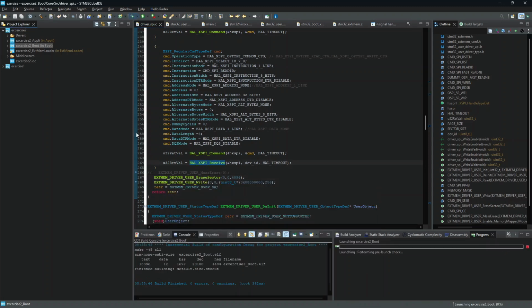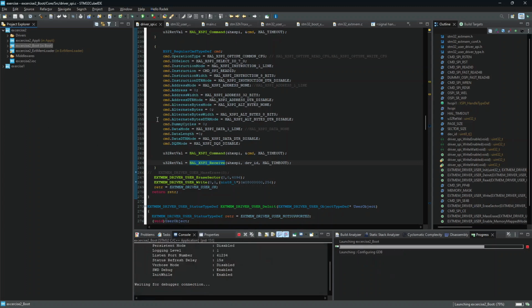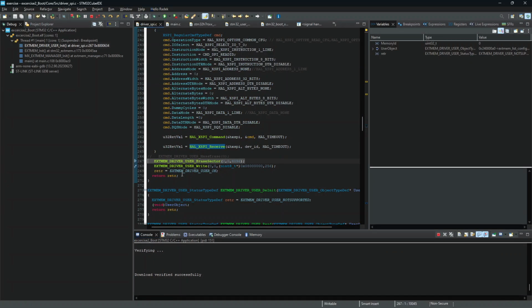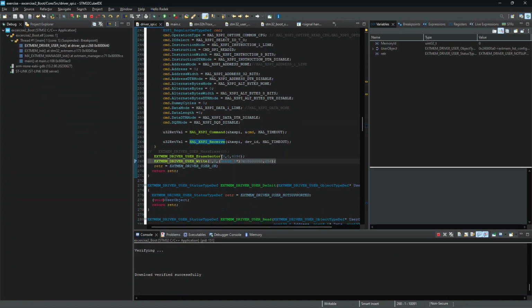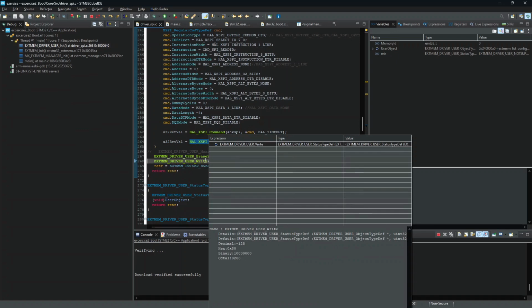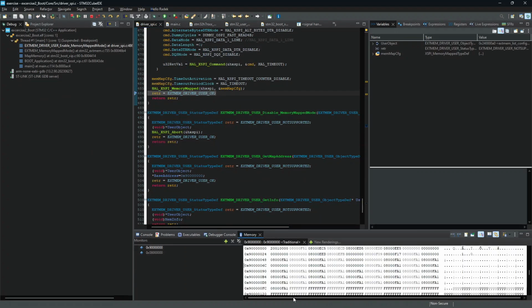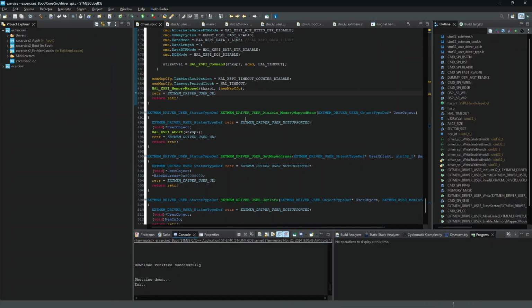I can again compile it. Okay, I can remove this one. It should be now much faster because I'm not erasing the complete 32 megabytes. And I can switch into the memory map mode. Probably I will see the same thing, but I see that now it was definitely erased because before it was program 512. So for me, it seems it's working.